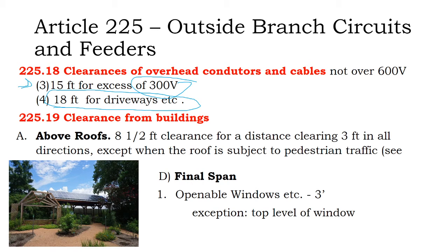There's ways to do carports at 150 volt circuits instead of 300 volt circuits. So there's a lot more wiring, but that might be a reason to do so, because there's cars and people underneath that could hit those posts, and limiting the voltage is going to limit the damage.